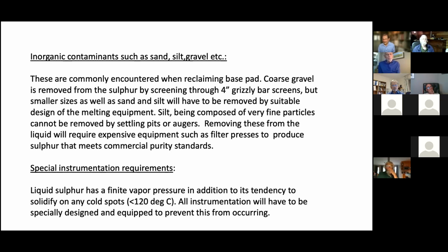And if you have an excessive amount of silt, even filtering, I've seen where your big 4-foot diameter filters you have to change every 2 hours, just not feasible. So the only option there is to use very expensive leaf filters where you have to use diatomaceous earth, and you have 12-hour operating cycles. Expensive operation if you have to remove silt from sulfur, but that's where the option of blending it with compost is a good option.